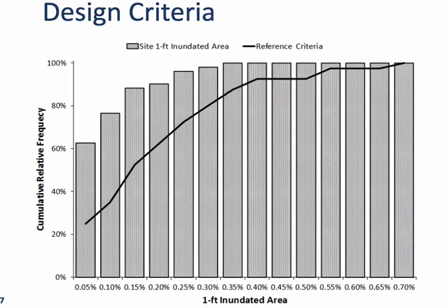Ultimately, we settled on a combination of slope, reinforcement, and cover thickness that would limit the deformations to an acceptable degree of pooling compared to that reference performance criteria. Again, not explicitly tied to exposure as ultimately we want to do, but one step closer to being able to accomplish that.